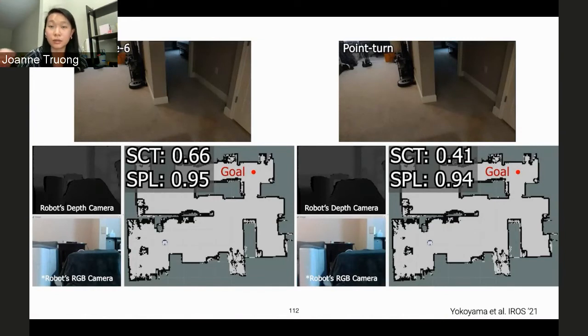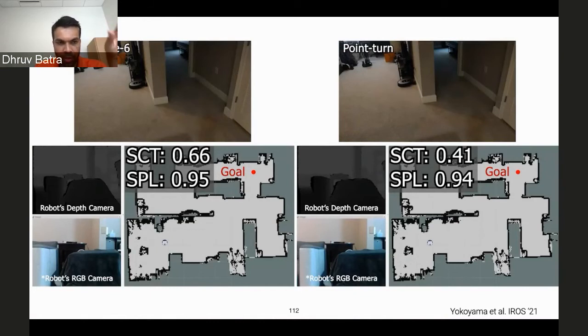So we inflate all the obstacles by a certain radius, and those become regions that the robot can't navigate to. If we know the radius of the Locobot agent, we can inflate all the objects by that, and so it won't be able to reach those locations during training time. That makes sense, and that's where a robot can go in simulation and where it can't.